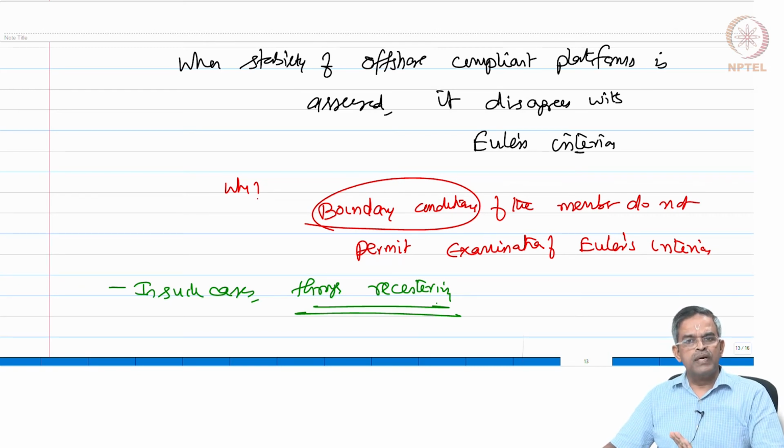That load capacity at the intended geometric form is not 0. It has some capacity. We all agree that the capacity is much lesser than the original load carrying capacity of the structural system in its original geometric shape, size and position, agreed. But the new geometric shape, size and position has some load capacity which is not 0. It is that condition which is called a stable condition.